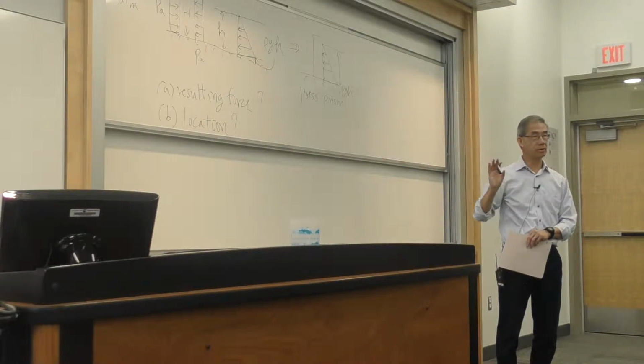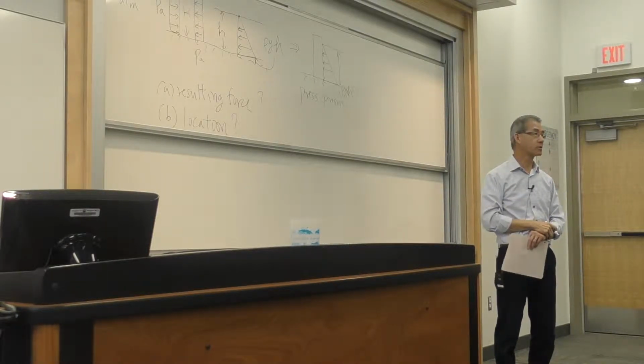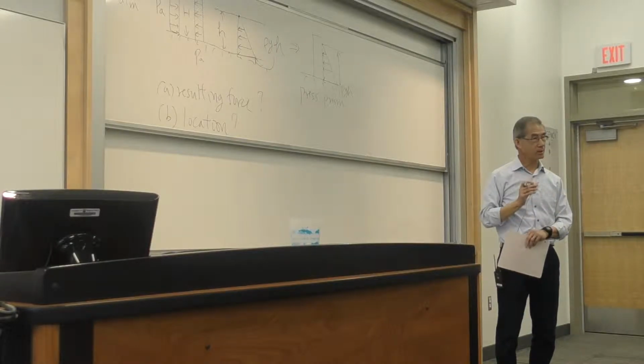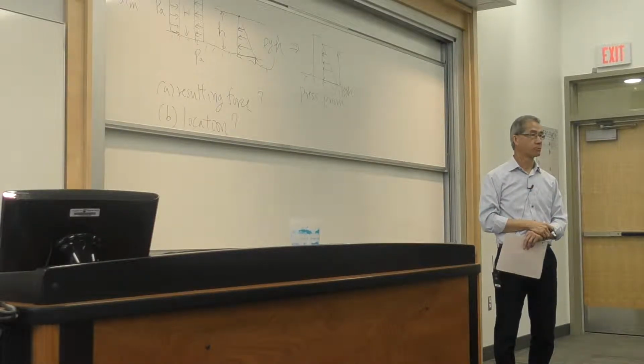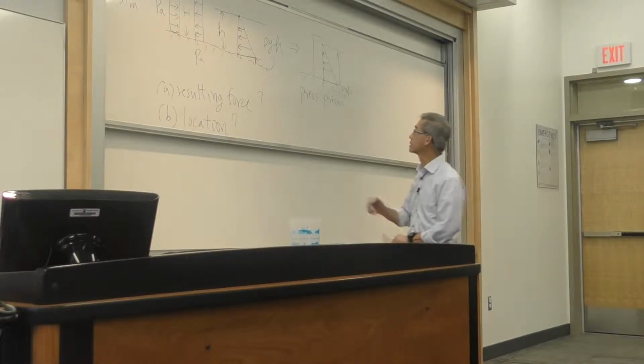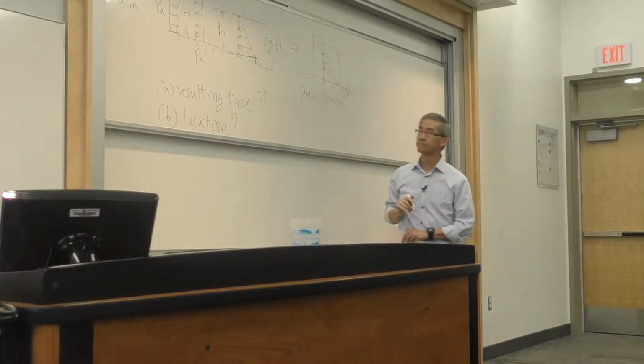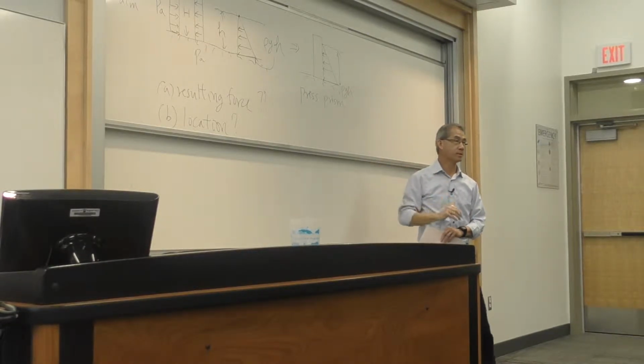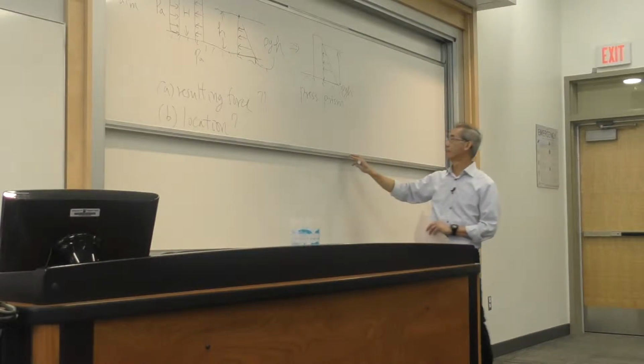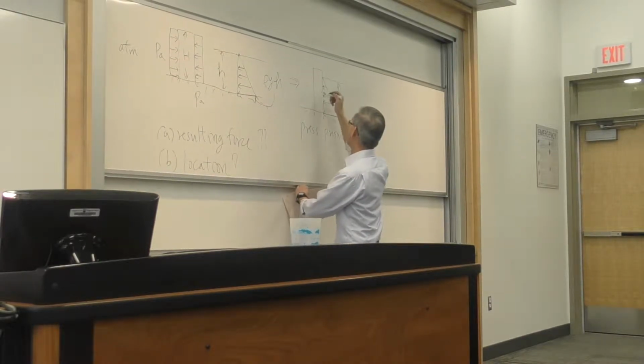So there are two ways to do this. One is the long way to get the resultant force. There's another, easier way, which is by inspection. Resultant force. A linear distribution: rho gh at the base, zero at the top. Height is h, small.